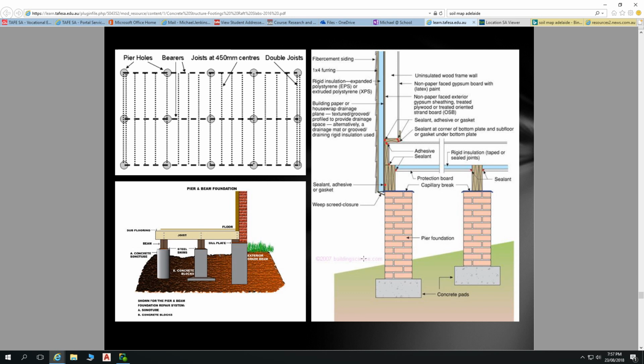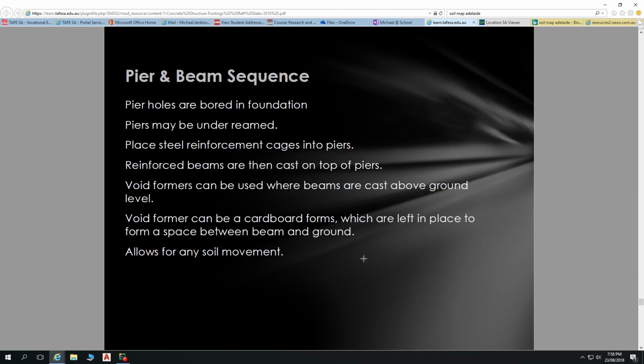But that platform flooring carried under the wall frame sort of tipped the scales of that, because you can't just take that flooring out and replace it with something easily because it's carried under all your wall frames. But that's your subfloor framing. In a nutshell, you've got your bearers, which happen on top of your piers, and then your joists, which happen on top of your bearers. And that's all determined from your timber span tables in AS 1684.